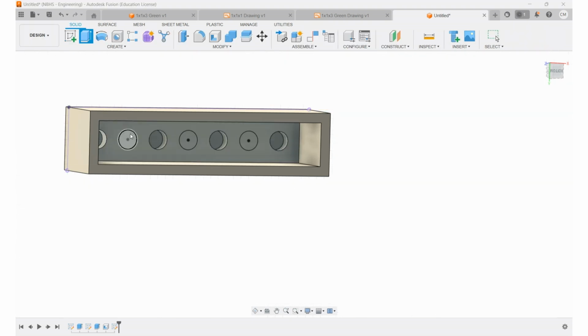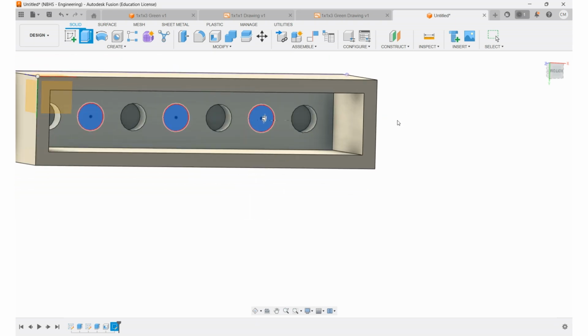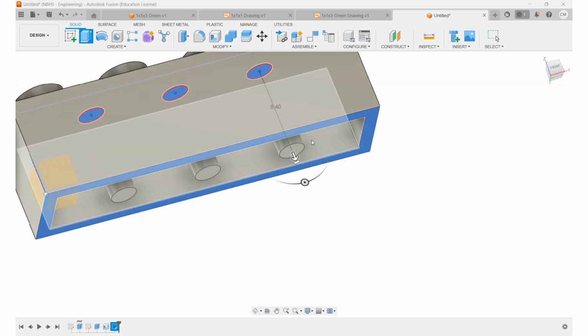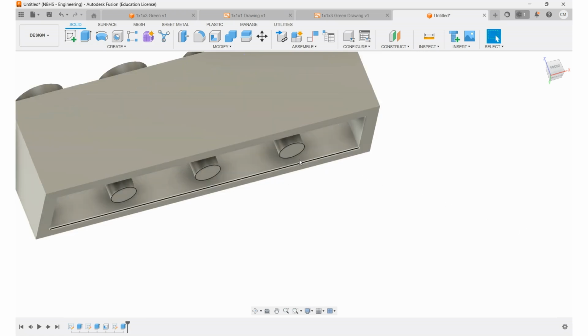So now I can come in and use my extrude tool. I'm going to click in each one of these shapes I've just created. Oh, did it wrong, so I just click again. Now, up to this point, we've used a lot of distance for the extent type. We're actually going to change this over to To Object because I want to tie this to this bottom edge. So let's go ahead and click that bottom edge, and you'll notice that those are there, even with it. Now that's useful here because it's a dimension we don't need to know, but it's even more useful in what I'm going to show you at the end of this video, okay? So I'm going to go ahead and hit OK.